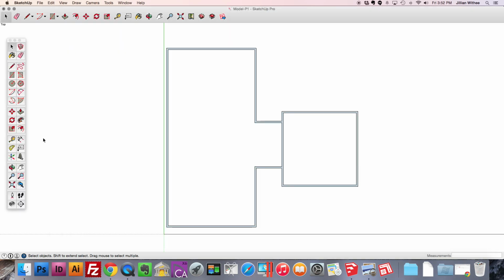So I'm going to come back to the drawing, click on the tape measure tool, click on that interior edge of the bottom wall, drag up, and you can see that as I'm dragging, a guideline comes with the tape measure. And it is aligned to the green axis as I'm dragging. So I am going to just type in 12 foot 9.25 inches and hit enter. And that gives me a guideline that is exactly that measurement from the bottom edge that I clicked on.